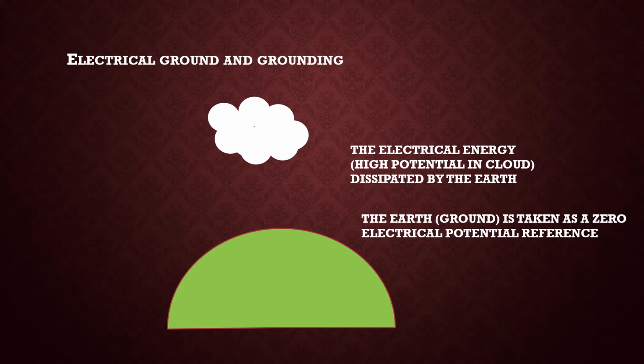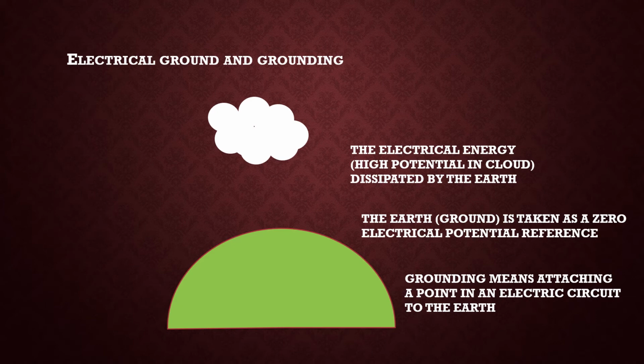So when you attach a circuit to anything connected to the physical planet Earth, you are grounding it and setting a reference to 0. In other words, you would take the frame of your building, you would ram it into the ground, and that would make an electrical connection, and then that building frame becomes your ground.